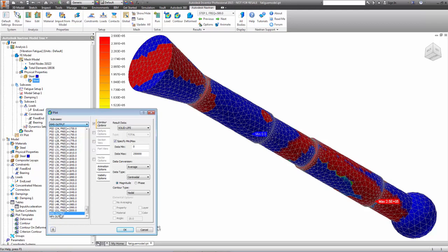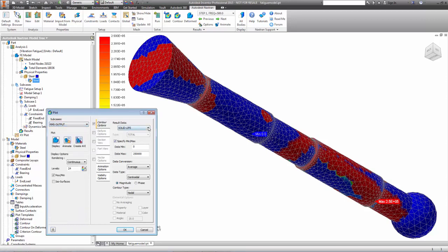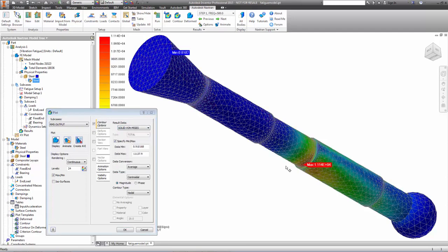Finally, you have the NPX, or net positive crossings, which are the pseudo-frequencies that represent the equivalent frequency the fatigue life was based on. So while the goal of this analysis was simply the fatigue life, a whole set of other useful information about the structure is produced along the way. Random vibration fatigue in Autodesk Nastran in CAD provides engineers with long-term insights into a product's robustness and dynamic behavior.